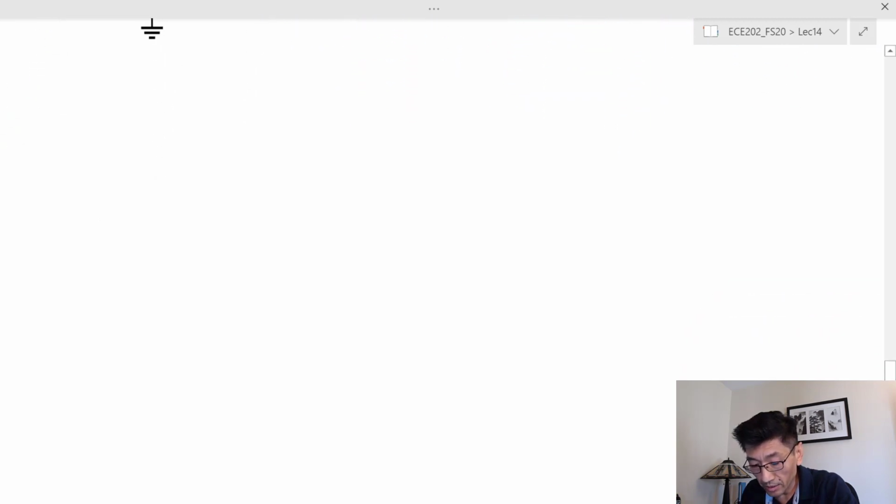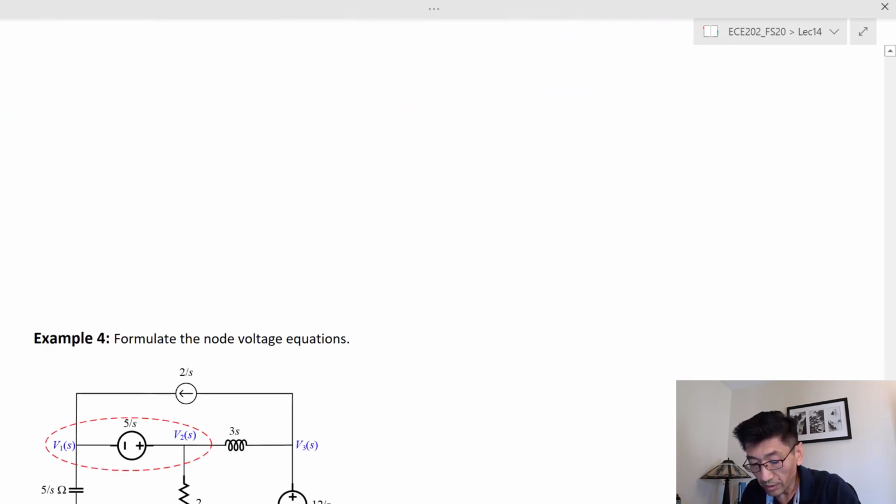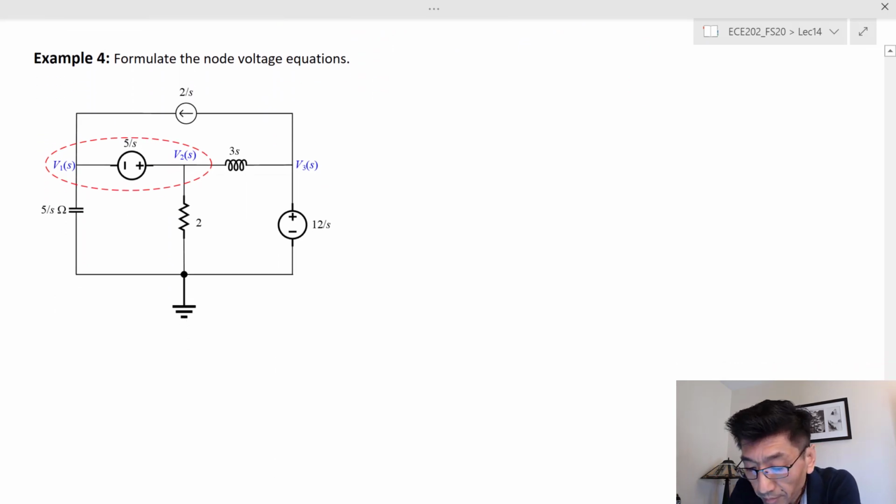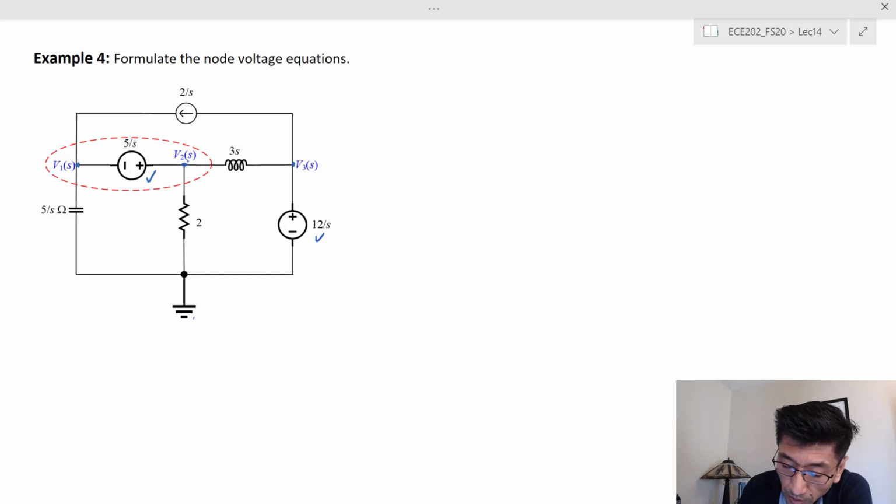And let's see the last case. The last case here is we have 2 voltage sources. Recognize this another voltage source, right? This is one voltage source we had before. In this case, I just chose this point. You can choose this point, or this point, or this point. No matter what you do, one of these voltage sources is going to be floating, not connected to the reference node. So what we do is we use this as a supernode.